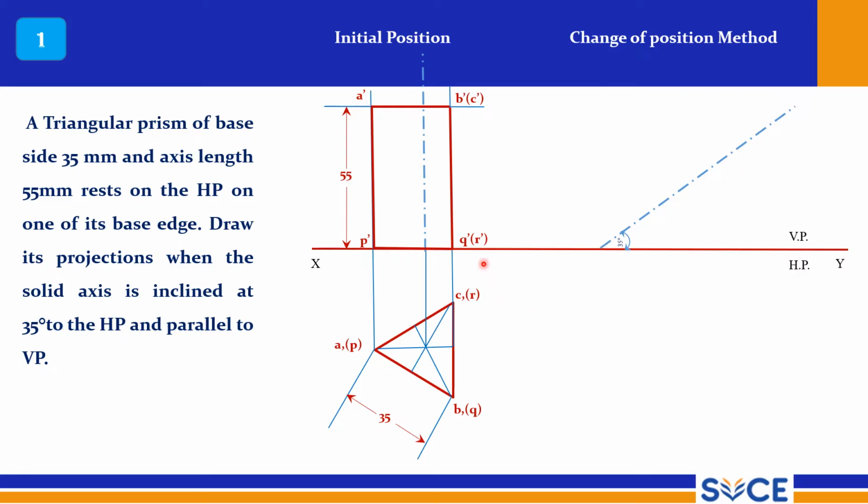On this line, you make sure that QR is sitting on the XY reference line, and to this line Q dash, R dash and P, this line should be drawn at 90 degrees. So to draw this, one simple way you can follow: this is 35 degrees, and if you draw a 90-degree line, this angle can be 180 minus 90 minus 35. So this angle is 55 degrees. So you can take 55 degrees and you can start the problem. And then it is easy, you will be having drafter, then you can draw the axis line.